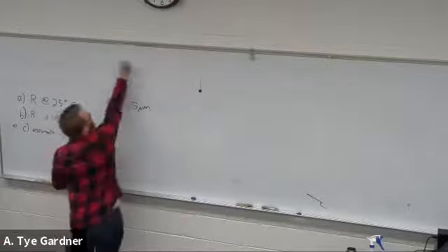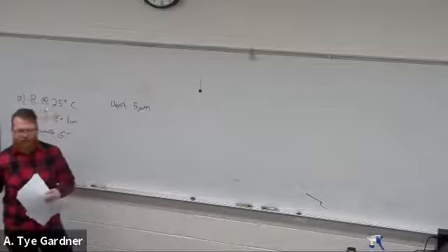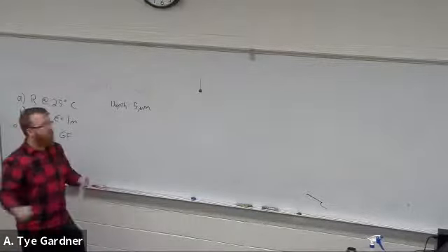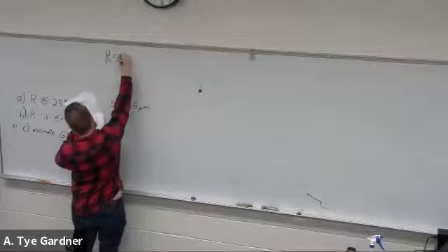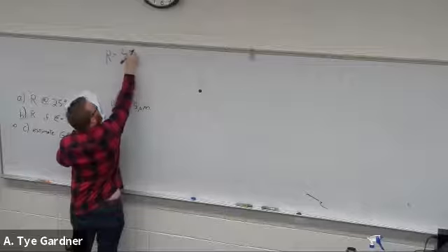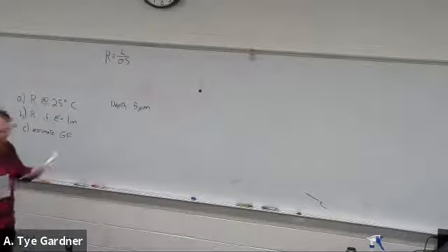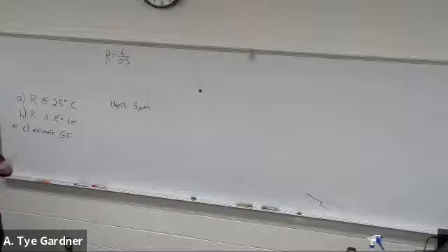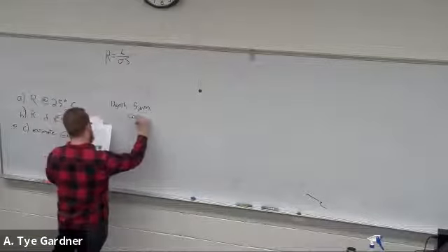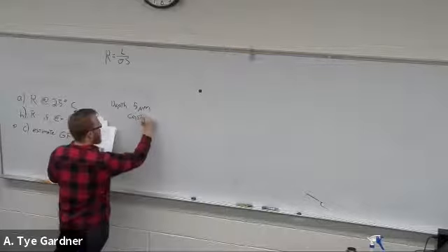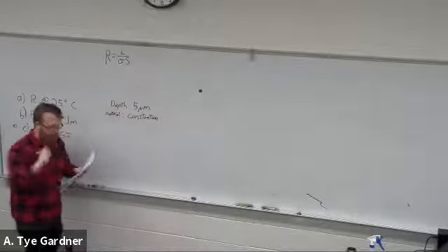This is the downside of not doing the derivation for you where the sensitivity comes from, because if you look at the resistance of a conductor, R equals L divided by sigma S. And the last thing that we need to know is that the thing is made of this material called constantan. Constantan is really cool because it is very temperature resistant.